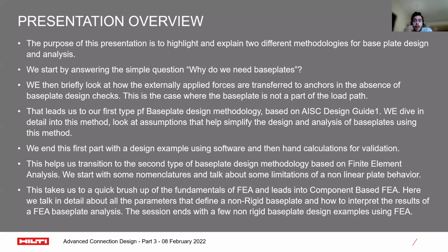element analysis. Here we talk in detail about the parameters that define a non-rigid base plate, and how to interpret the results of FEA. I will start to refer to it as FEA instead of finite element analysis all the time. So, FEA baseplate analysis. This session ends with a few non-rigid baseplate design examples using FEA through our software.